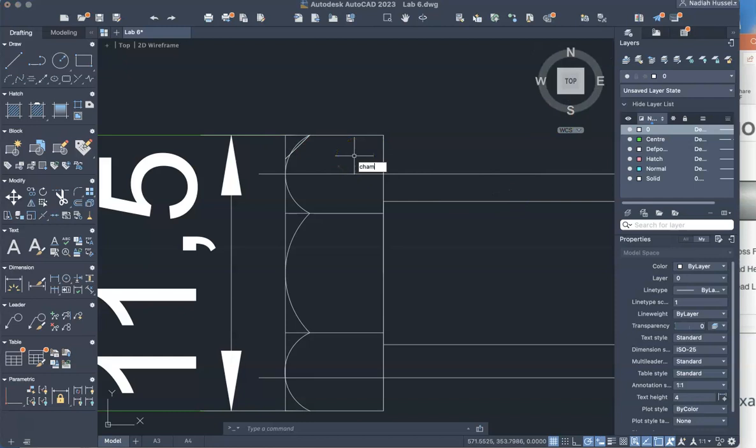So now I'm going to make my chamfer slightly smaller. Just now it was 1, so now I'm typing capital D, and the first distance of the chamfer, let's go with 0.75 and 0.75. Okay, so this is going to be it. Okay, so 0.75 does not really overlap. So let's try another value, maybe 0.6.